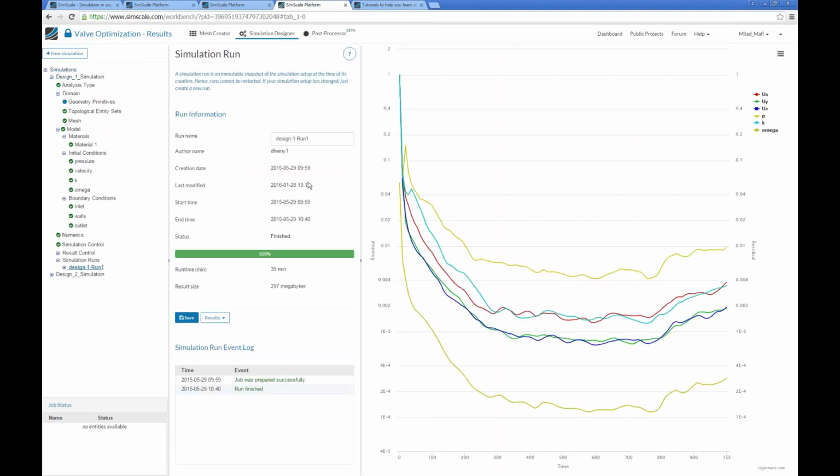And then you get this plot here. This is a convergence plot. What it shows is, for every iteration, for every step, how the average error changed. The average error became smaller and smaller and converged here, so this is looking good. For example, the average error of pressure is smaller than 0.01, and the average error of velocity in y direction is about 1e-3.